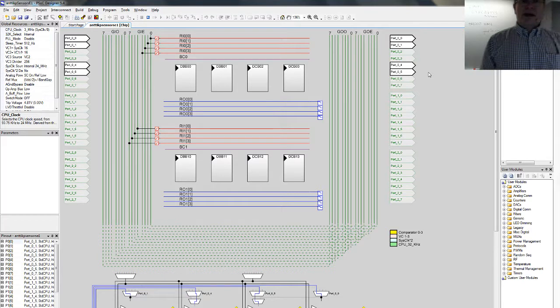Then there are some switches, or lines with switches, digital lines. And the vertical lines here are each bit on odd ports or each bit on even ports. So you can connect, for example, any pin of port 0 to the corresponding pin in the global in even lines.